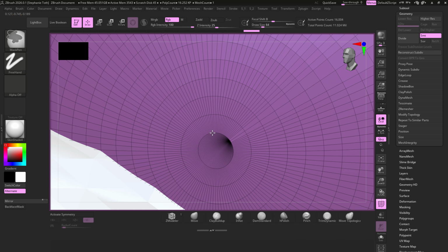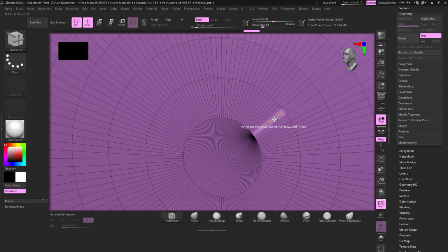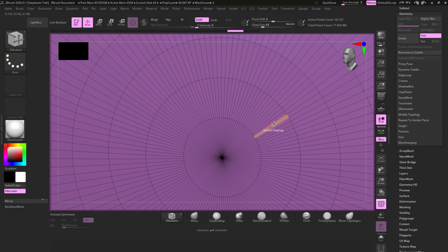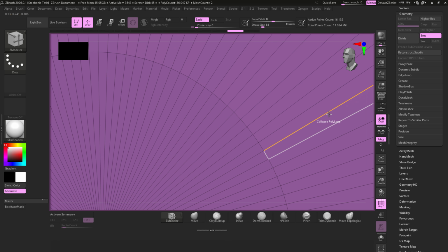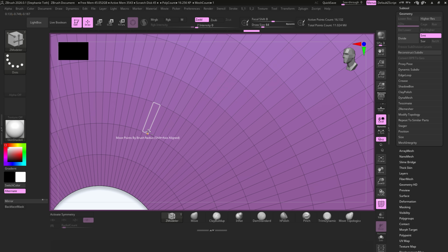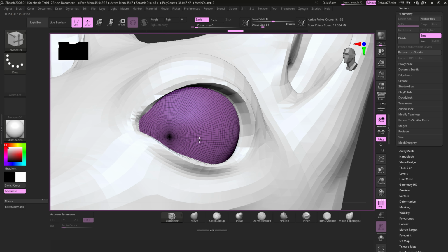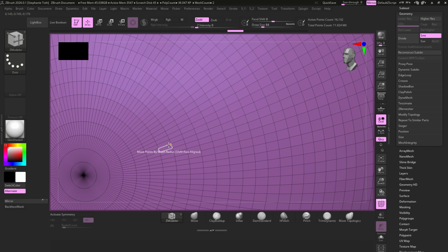But you'll notice here when I did that on this area, I sort of collapsed that point here. So sometimes it's not exactly worth it unless I delete this poly loop. And if I zoom in here and delete that, and then I can start collapsing these, but then I would have to come in and then bridge them again. So I think I would probably leave those the same, but if you wanted to, you could collapse some of them that go around this way.